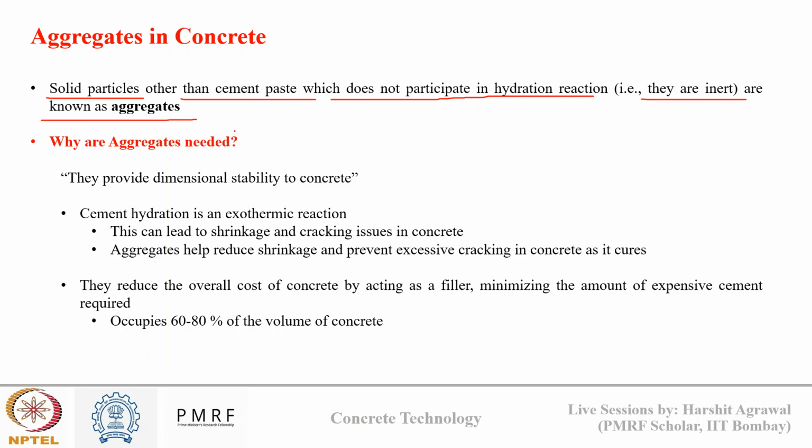Now even though they are not contributing in the hydration reaction, then why are aggregates needed? In simple terms, they provide dimensional stability to concrete. Why is this important? Because we know cement hydration is an exothermic reaction, and this can lead to shrinkage and cracking issues in concrete because of heat release from concrete.